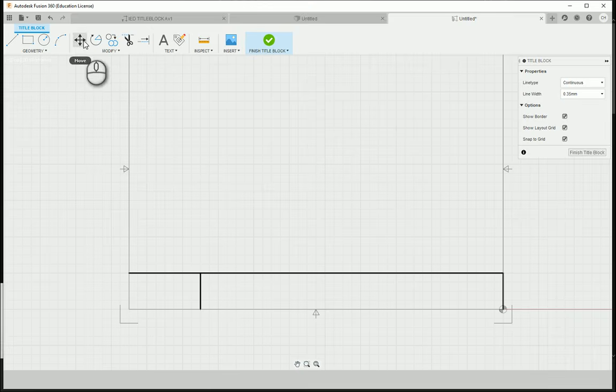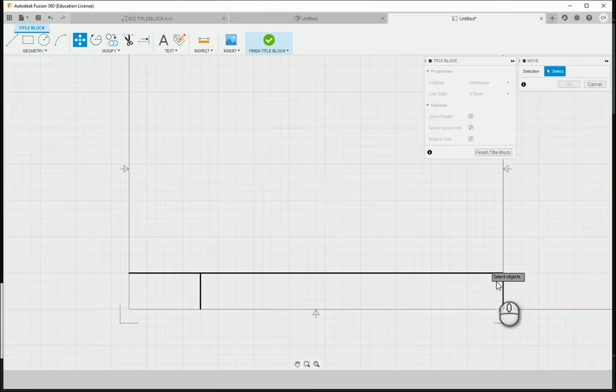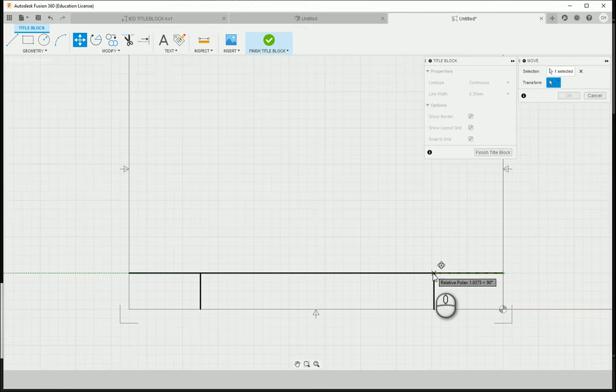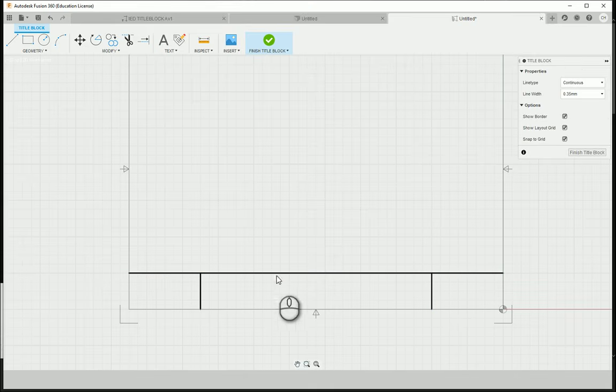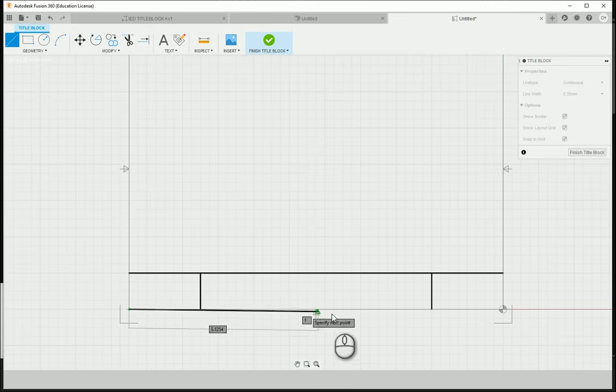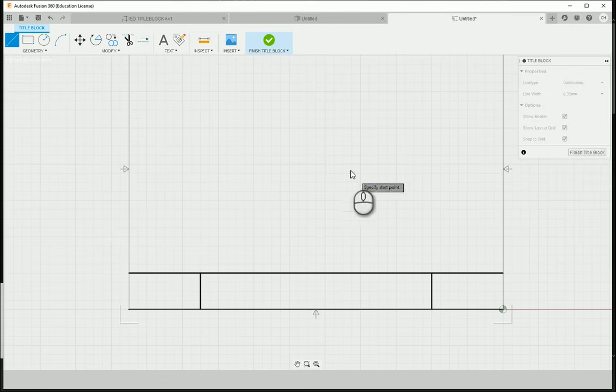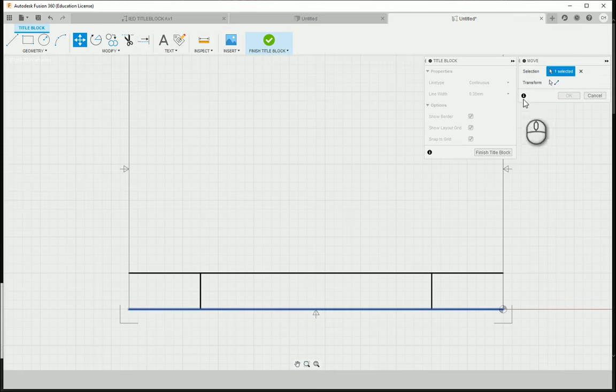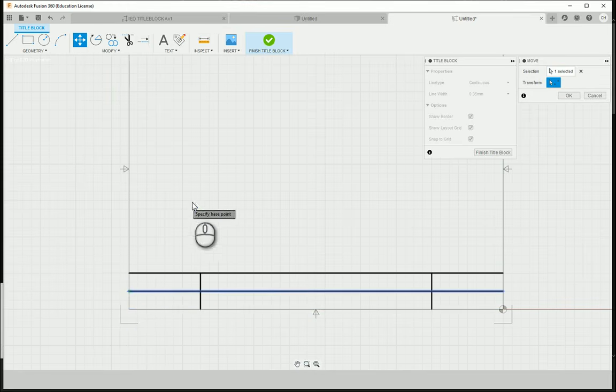I'm going to run my move tool again, so you'll see move is also M on your keyboard. So getting used to the shortcuts is very helpful as well. I'm going to do 2 inches from this end as well, so equal spacing, and then I'm going to click line. And then right at about the midpoint, or if you want to make sure that you're getting exactly 1/2 inch, we can always draw that line in, select it, and then move it up.